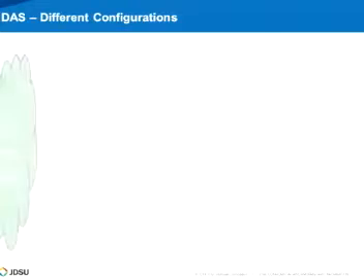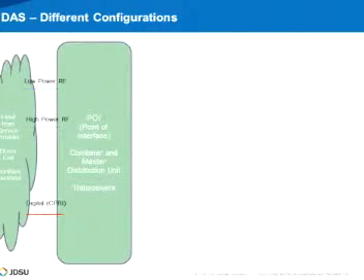As far as DAS and different configurations, it pretty much all starts from some type of a feed from either the service provider, a donor cell, or just a front haul backhaul type of connection that gets you back into the cloud of the internet. It can be either low power RF or high power RF, and even today we're now starting to see signs of digital CPRI being a new way to come into the point of interface, where on a DAS system you have combiners and the master distribution unit, and then various transceivers.